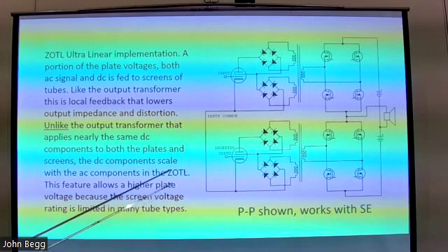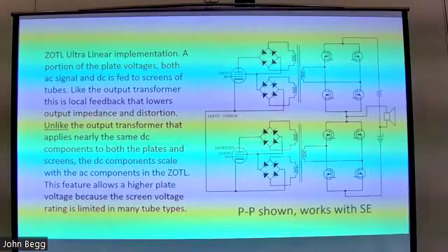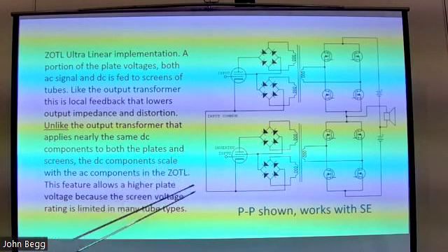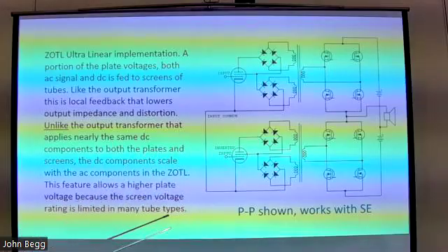If I put all the turns on one winding, there's leakage inductance, which ruins the fidelity of the 250 kilohertz square wave. So the way to get around that largely is to break that down into small, low number of turns windings and put a whole bunch of these bridge rectifiers in series.